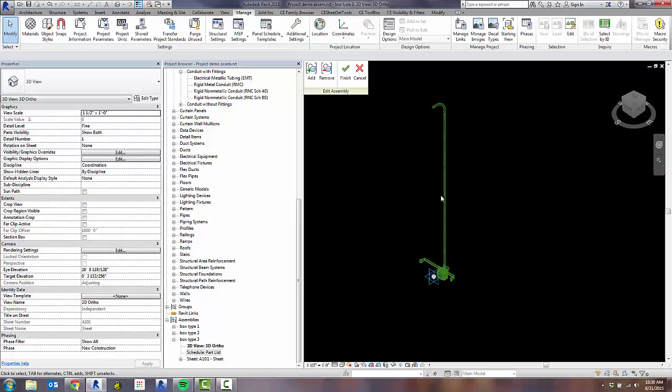So the second part of this video, I'm going to show you why we went away from the system family conduit, and not just because of the assemblies, but you'll see the big difference here. So I'm going to cancel out of this.